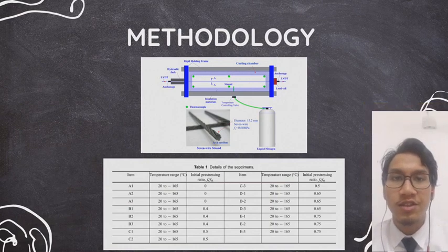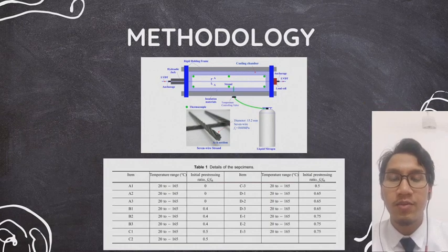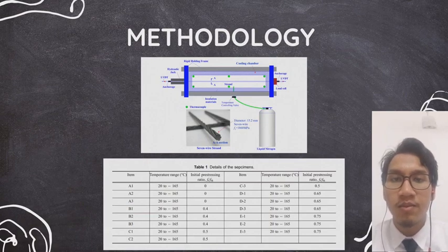During each test, the steel strand was first put into the cooling chamber and installed on the reaction frame. Next, pre-stressing was carried out on the steel strand by the hydraulic jack. Considering the contracting stress due to low temperature, a gap of 30 kN to each target pre-stressing level was reserved for the test before the cooling process. After the pre-stressing, liquid nitrogen was injected into the cooling chamber. 6 thermocouples were distributed on the surface of the steel strand to monitor its temperature.